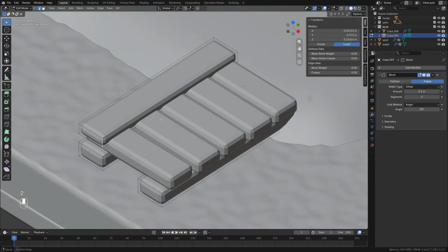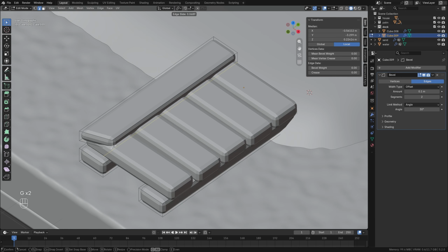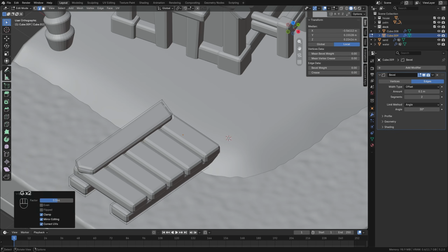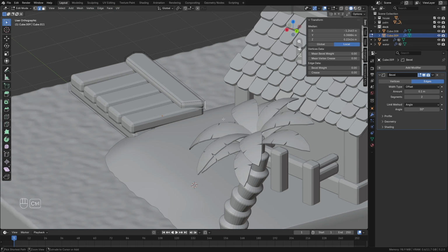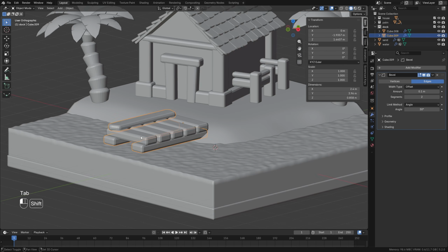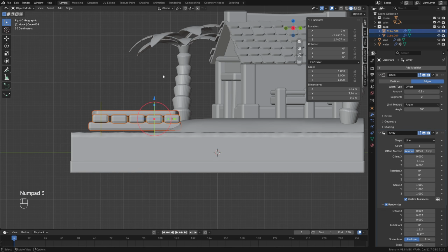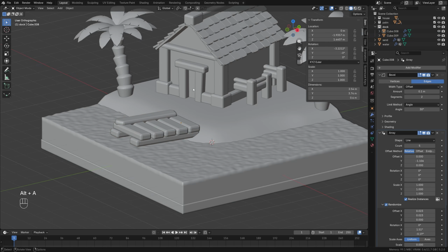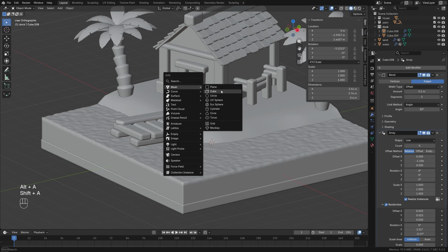And now, in edge selection mode, here we will press G twice, shift the edge. And here we will select the edge, press Ctrl plus B, and split the following angle. Exact same way here, G twice, shift it a little, select this edge, Ctrl plus B, and set up the bevel. Now both these given elements we will select, turn them a little, press R, raise our bridge a tiny bit so that it wasn't completely flat, and also add a cylinder here.